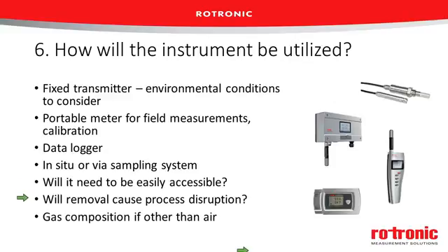Will removal cause process disruption? If your application is some type of production that goes 24 hours a day, 7 days a week, 365 days a year, you probably don't want to disrupt or stop that process just to calibrate or repair that instrument. Some instruments have an option where you can do a hot insertion and hot removal, or it may be cases where you have a removable probe that you can quickly replace. It's just something to think about, because you don't want to disrupt your entire factory just for an instrument change.